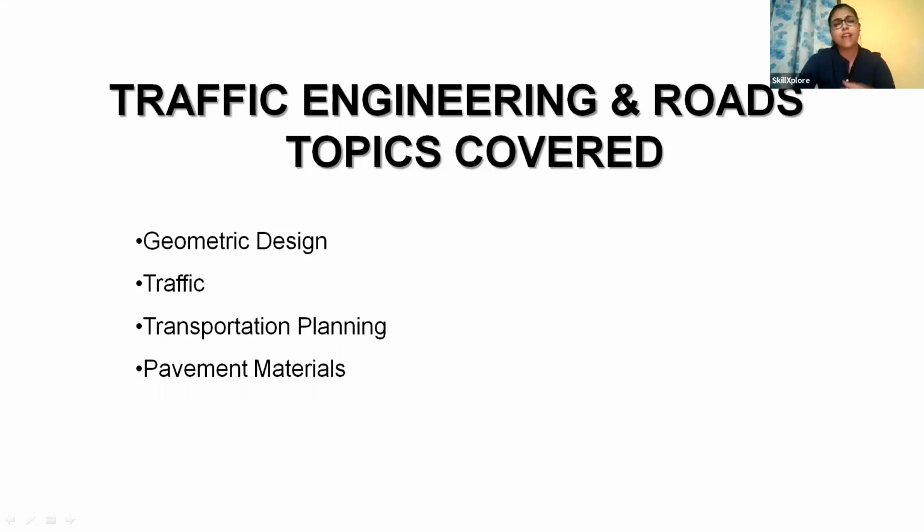And the various other considerations are the curves, horizontal curves. If there is any curve in our road, can we give the curve abruptly? It is not given abruptly. Some transition is given for any particular curve. If it is given abruptly, then accidents may occur. So that has to be considered. Then the speed of the vehicle, the design speed, which speed we have to design for, that will be there.